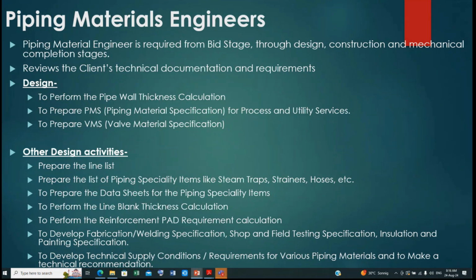Also, in a few companies the piping material engineer assists in taking out the piping MTO, or in a few companies there is a separate team for the piping MTO. Those piping MTO designers or engineers will take out the quantities of the piping components like pipe, valves, and fittings from the P&ID, and all this data will be consolidated by a piping material engineer in different software.